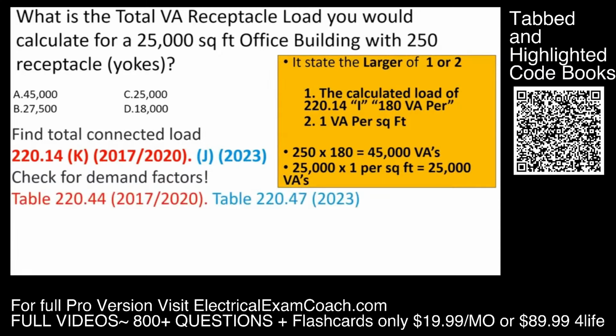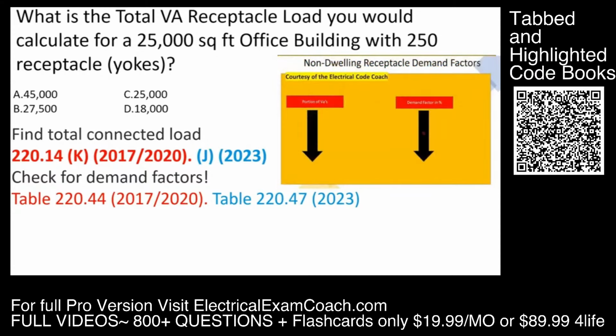That leads us to table 220.44 if we're in the 2017 or 2020, and table 220.47 if we're in the 2023. Same information, different title. When we get there, we're going to see it's very similar to table 220.42 and 220.45, depending on what code cycle we're in. We're going to start on the left-hand side, and it's going to tell us our portion of VAs, and then on the right side, it's going to tell us our demand factor in percentage. And this table is for non-dwelling unit receptacles.